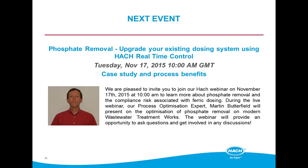Well, if you've got an online analyzer on the activated sludge effluent, then you can do a straight mass balance, and you're in a nice position that you've got complete visibility of how the process is performing. If you don't have that, then really the next best thing is, if you know that you're getting problems, you could adopt a 24-hour composite sample, and you'd have to take hourly spot samples, which isn't ideal.